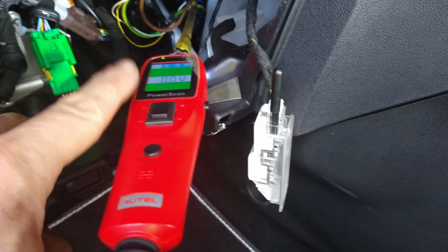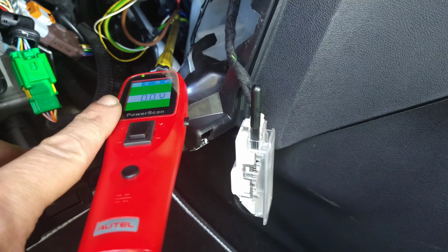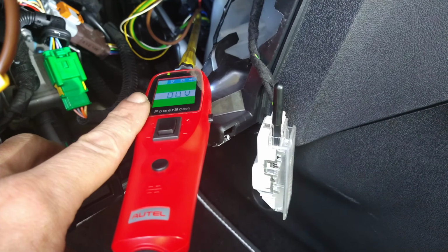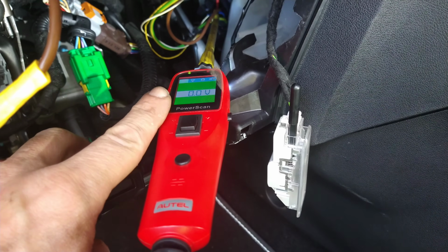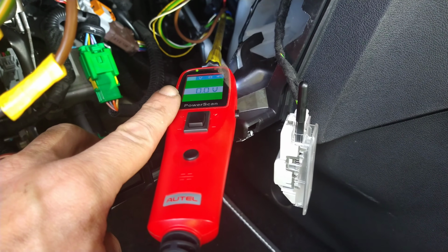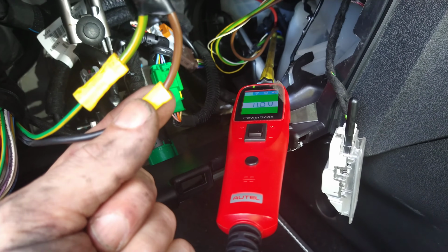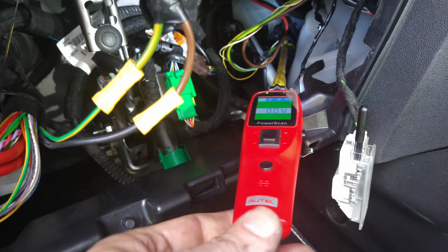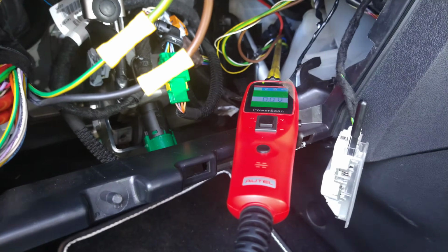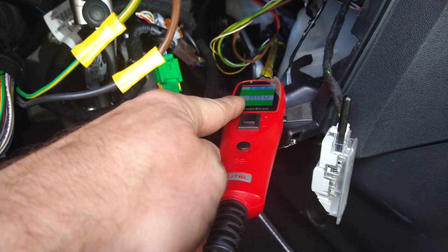This ground there could be a fake ground, because when there's no power, when the ignition's off, that was showing ground through the power supply wire, the brown wire. Going all the way back, the power becomes a ground, or lights up like it's a ground when there's no ignition. So I'll put the ignition on and check we've still got a green here.